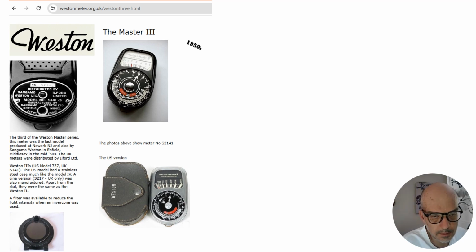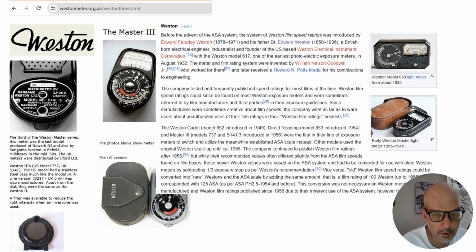Of course, today we don't need light meters because we have active pixel sensors that can measure directly how much light they're getting. We don't get one shot. The photographer back in the film days had to get the exposure right, or he'd wasted some film, but we don't have to worry about that today. But we do want to worry about how much exposure we should use to record the film, and in order to understand that, we need to understand how the illumination translates into signal on the focal plane.